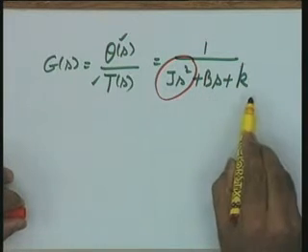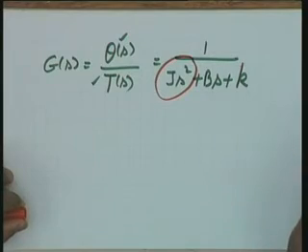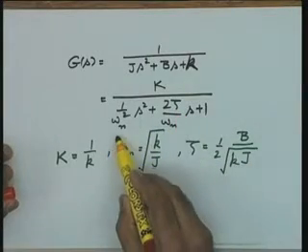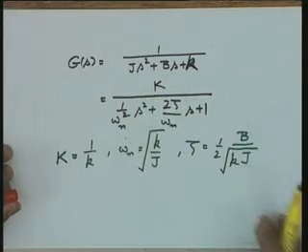Again J, b and k are the specific parameters of the system under consideration. I am interested in general parameters, so that those parameters have physical meaning and they become applicable to any system we come across. And the general parameters, you already have the information about those parameters. As I said, it is a review sort of thing. To put it in the control system setting, the general parameters as you know are omega n, the natural frequency, zeta, the damping ratio and K, the system gain.